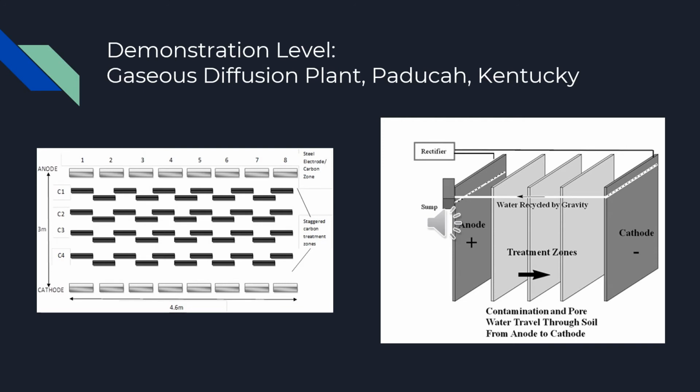The electrodes had 8 steel panels installed next to each other with a gap of half an inch. Each panel was 16 feet long and 18 inches wide. Fluid was circulated with tubes and pumps. A collection system was designed above the soil to collect vapors containing TCE. The test area was subjected to 40A and an initial power of 138 volts for the first month. Then the voltage was reduced to 105 volts.